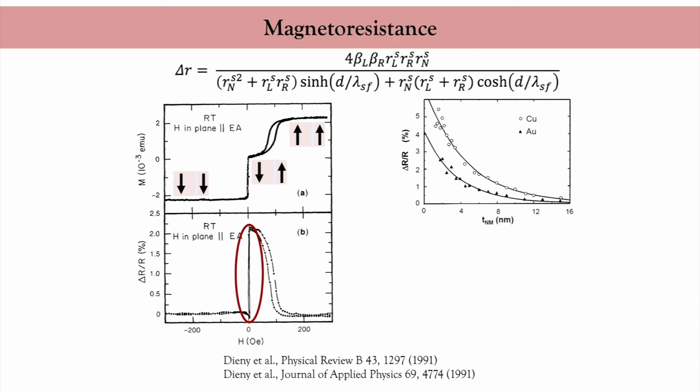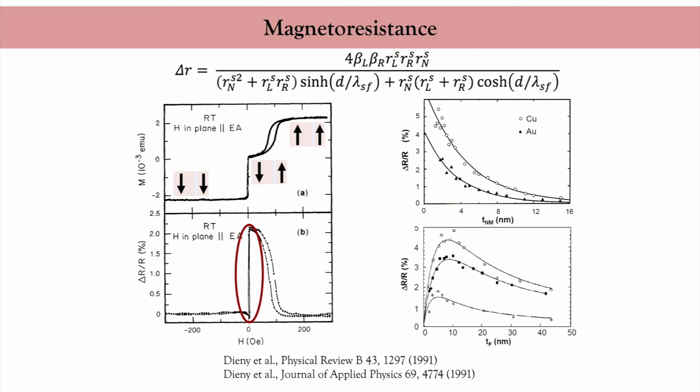Similarly, if you increase the thickness of the ferromagnet, you first see an increase of the signal because you improve the spin polarization of the flowing current. But after a while, adding more ferromagnetic material does not increase the spin polarization anymore, and on the contrary, enhances the overall resistance. Therefore, you end up with a steady algebraic decay at large ferromagnetic thicknesses. So this tells you that in metallic spin valves, you have to be very careful not to add too resistive materials. Otherwise, you simply quench the signal. Hence, you need to smartly engineer the device and choose the proper materials combination to optimize the spin polarization.